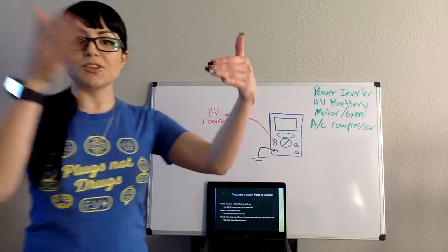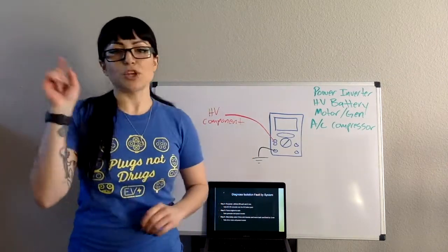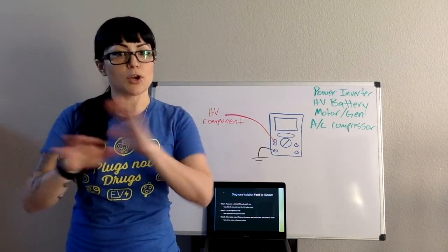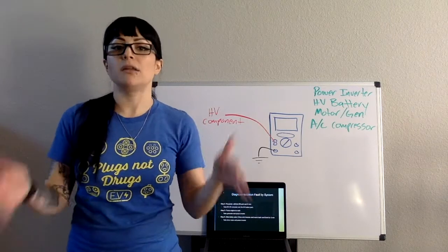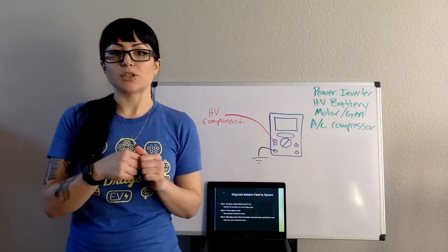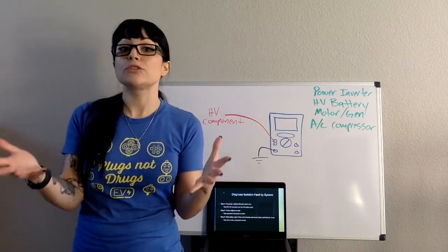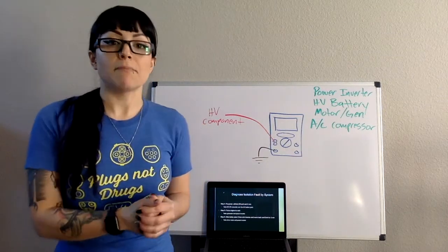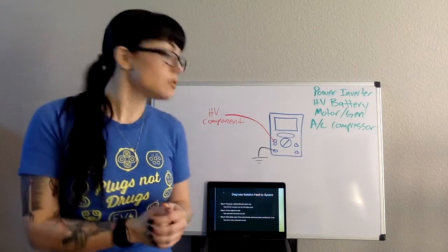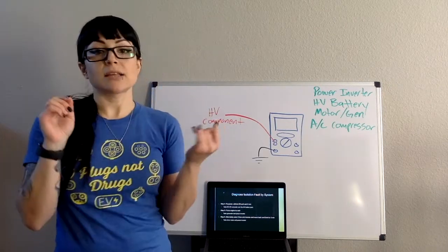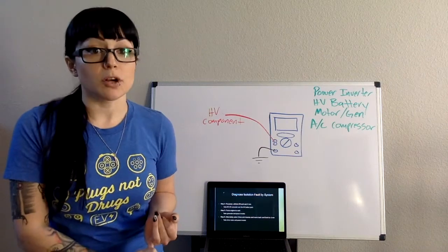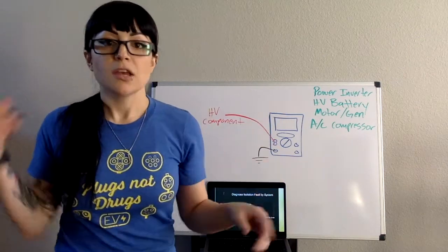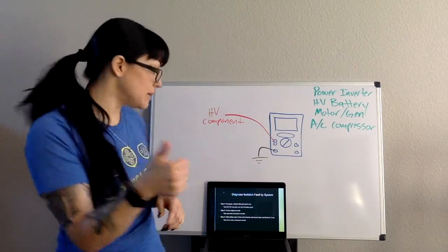So back to our step 4, right? We just powered on the vehicle. I'm waiting 2 minutes. All I did was power it on. No accessories, nothing on, just pressed my ignition button with the foot on the brake, trying to ready up the vehicle. If I get a malfunction indicator light with an isolation fault during this time, it is going to be from the DC to DC converter, because now the DC to DC converter is powering everything else. So that's one area it could be.